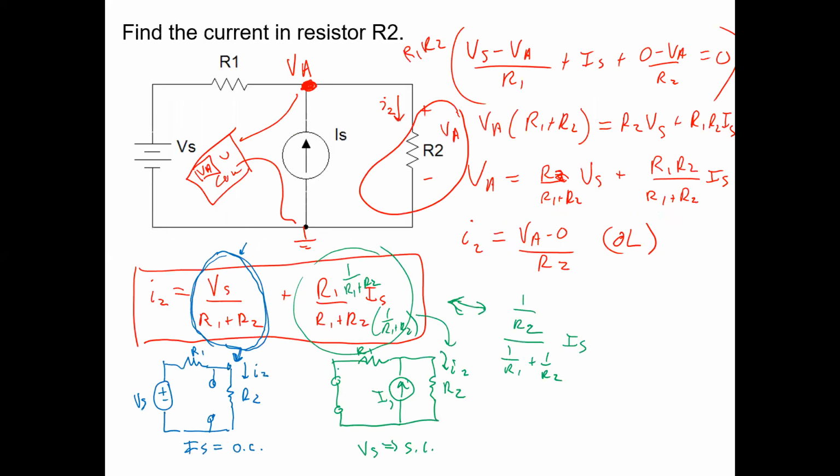Why is a voltage source equal to 0 the same as a short circuit, anyway? Why is this the same as turning a voltage source off? Well, what's the voltage drop from here to here when you have a short circuit there? It's 0. So that's how you can impose a 0-volt drop across 2 points of the circuit. And so that's like turning off a voltage source. You're assigning that thing to 0.